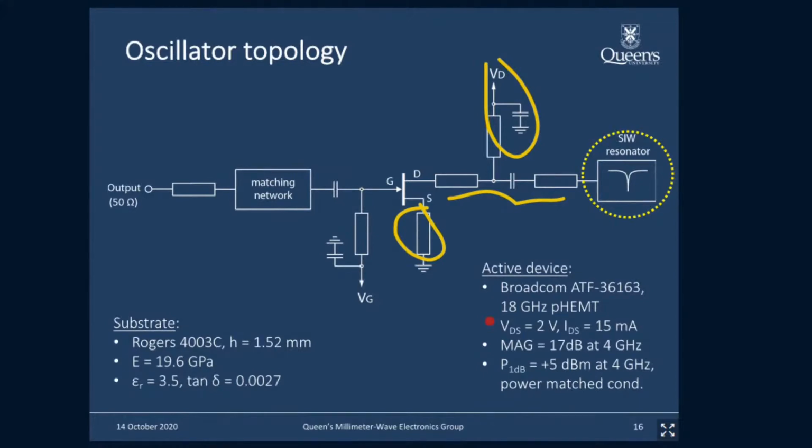So let's talk briefly about the resonator. I am actually missing some images here, so I want to skip over that and go right to this page. So this is the resonator. A substrate integrated waveguide is a type of transmission line used in printed circuit boards that has some similarities with rectangular waveguides used in microwave engineering. Now, a rectangular waveguide is a hollow pipe, and it can have different cross sections. Rectangular is the most common. You can also have circular, and these waveguides have a lower cutoff frequency. Below that cutoff frequency, you don't have any propagation. So they start propagating above a certain frequency.